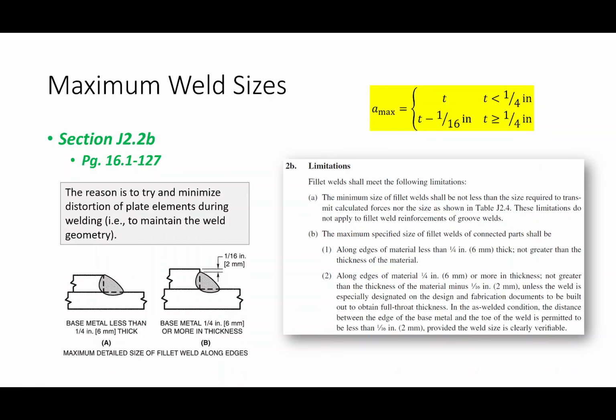And then because this is melting, that 45, 90 that you were assuming, and that weld size that you were assuming, suddenly the weld geometry is sort of deformed and kind of weird, okay? So what I'm saying is that if the weld gets too big, you're going to start to melt the plate, and then suddenly that 45, 90 geometry isn't going to be maintained, okay? So here's what the spec says, okay?